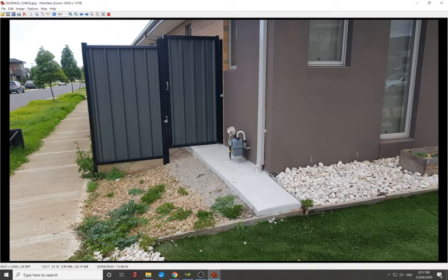I personally, yeah, like a lot of other things you could do there. But anyway, you can see this is all concrete on the wall here too. It's built up there. And on the render it's worse because you won't get that off. You acid wash it with the render, you're just going to get discoloring of the render. Not all render discolors with acid on it, but some do. So you just got to be careful.